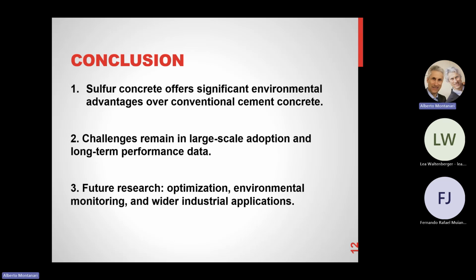Yes. So, why is it not widely used? Because it needs some equipment to heat the sulfur and make it go from solid to liquid, and then it can be combined with the aggregates and some additive materials to produce the final product as a concrete.